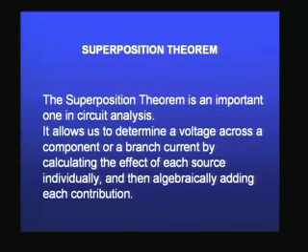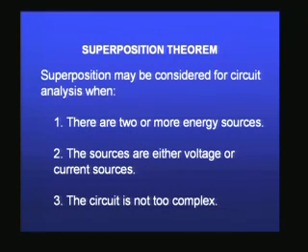So let us look at the superposition theorem with reference to electricity and electronics. In what way does it help? It helps in determining the various components of voltages and currents in different segments of a circuit, in branches of the circuit. So it is very important and very useful. Now how do I do that? In any given circuit you can have more than one voltage source. You can have 2 or 3 voltage sources, you can have several resistors. Now let us confine ourselves to simple cases of resistors and voltage sources. How do I find out the current through any one resistor due to the presence of several voltage sources?